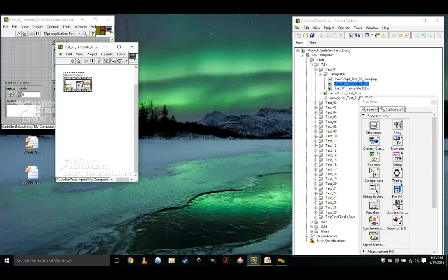Do I have to have an MXW framer? You don't. If you don't use the MXW framer, it'll slow it down because then it has to do a copy and paste instead of a move. The frame has to be either a flat sequence or a stack sequence. I would recommend a stack sequence until LabVIEW does away with it, because stack sequences are smaller and faster, and it's a single frame. No, MXW Framer is what the Codegen engine looks for. You have to have it called MXW Framer.